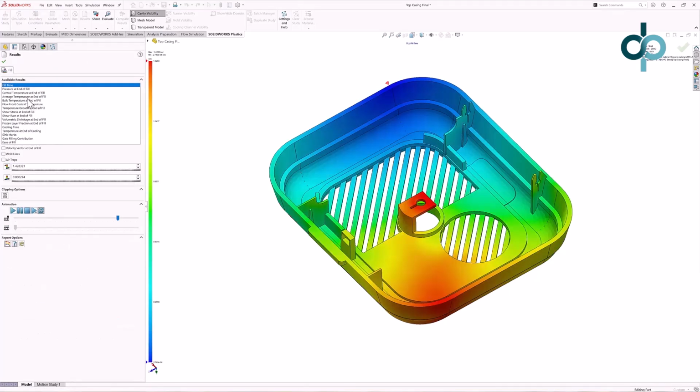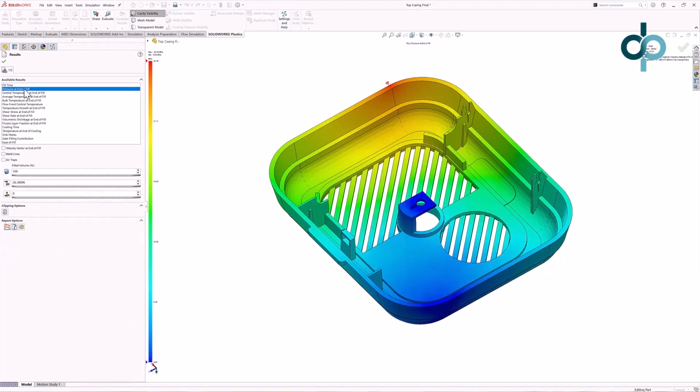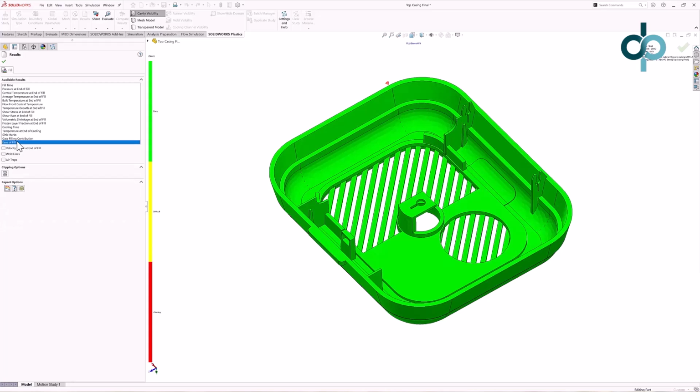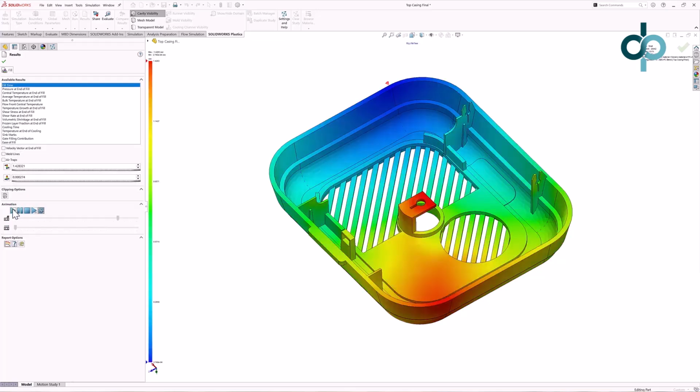Now let's go into the details here and see what's the pressure value. And we're able to cut that down significantly, making sure everything's green. Of course, I always want to know if this can be filled. So that's how SOLIDWORKS Plastics can be used to help guide you to better understand the implications that your design decisions have on the injection molding process.